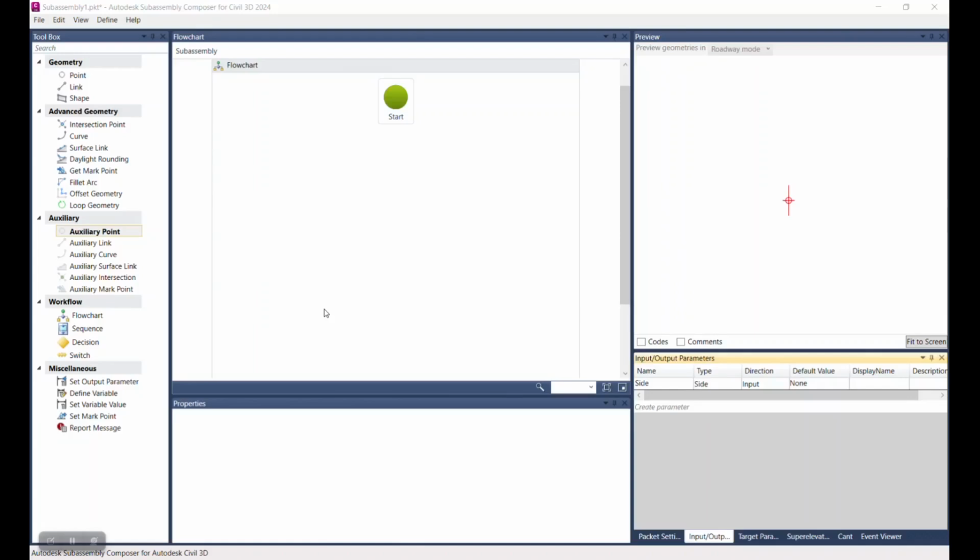Okay, so from our first step, we determined that the first thing we needed to get was the wall bottom at the back of the wall. And for that, we'll be using our first input, and that is a wall thickness, which is usually something we already know. And so we come over to this part of the screen, we create a parameter. We're going to name it something that makes sense, wall thickness.